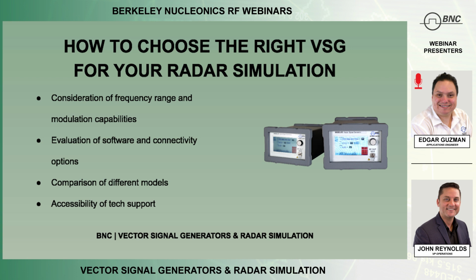So, how to choose the right VSG for a radar simulation? And I touched on this earlier. It's the specifications of the system, and I believe I have it here. Let me look at this. Yeah, so it's the same features that we always get asked about. The frequency and its stability and accuracy. Big one is phase noise.